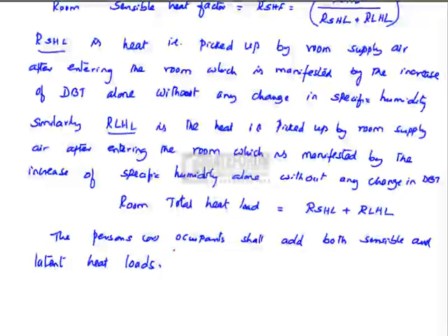When the sweat evaporates, the humidity content of the room will increase, and they will add the sensible heat also because of the temperature difference between the human body and the surrounding air.